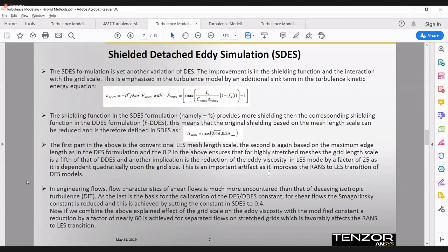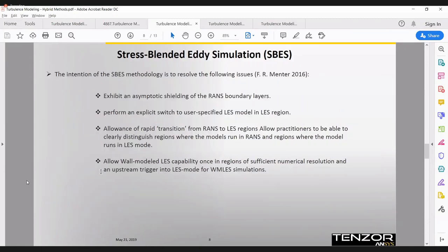I mean, it's usable, but you will not be able to validate a posteriori. You know what I mean? Do a validation afterwards with the turbulent content that you get. What you can do with the WALE model or perhaps even Smagorinsky in some cases.